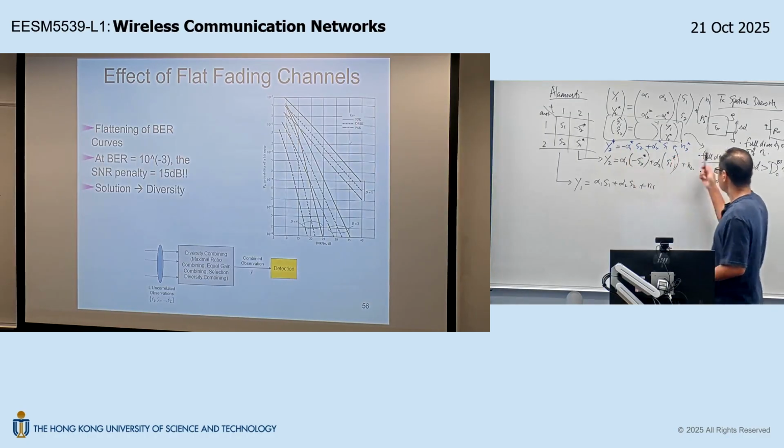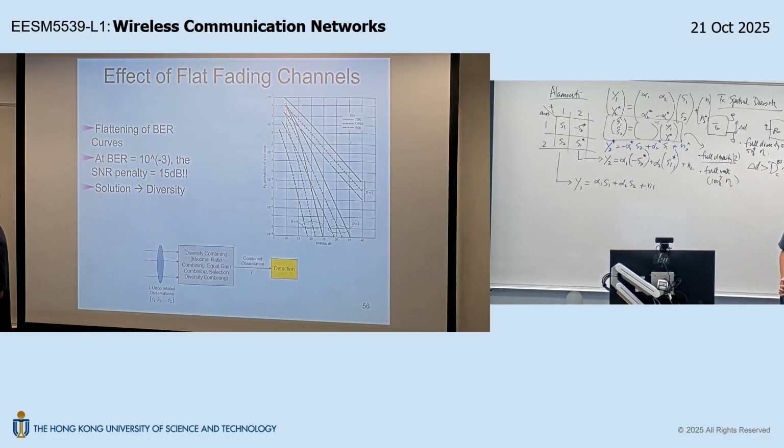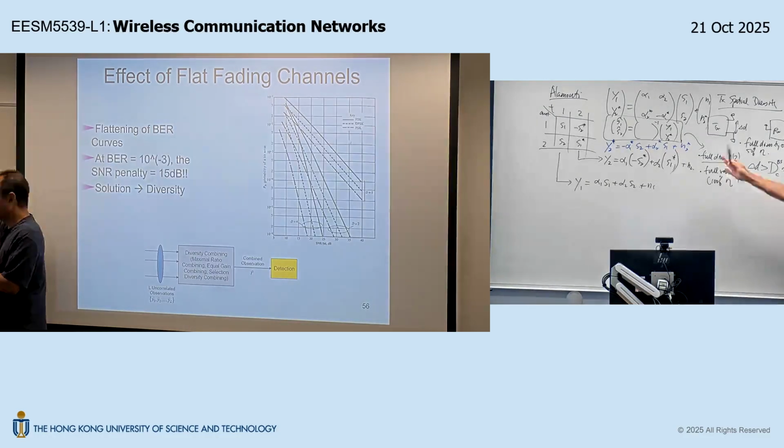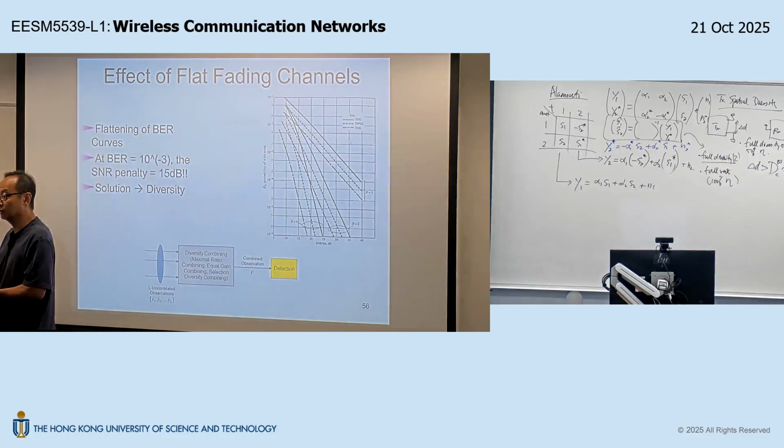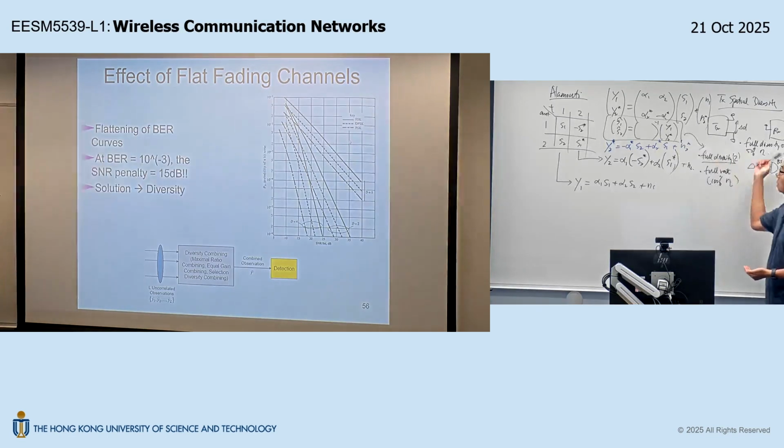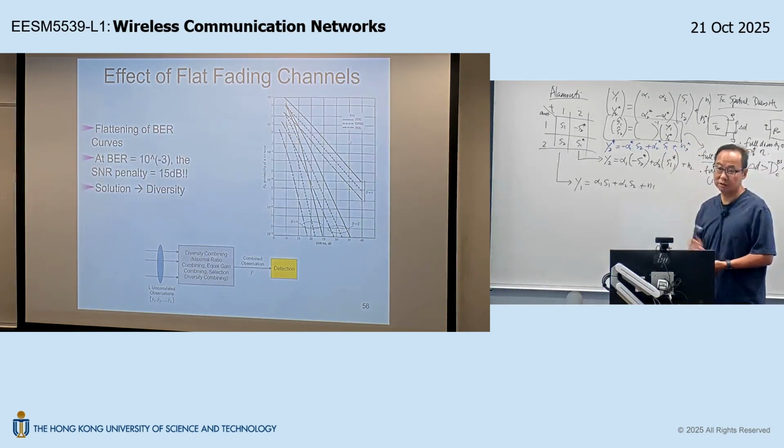And this performance, the same as received spatial diversity, only works for a small number of transmit antennas. It only works for 2 transmit antennas and 4 transmit antennas. Okay, so for some other numbers of transmit antennas, it wouldn't work this way. So it turns out that these 2 topologies are not the same. They are not symmetrical.